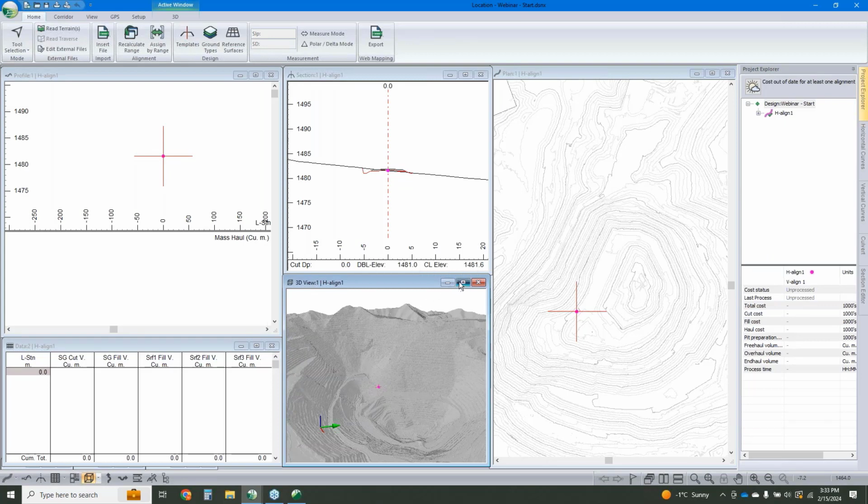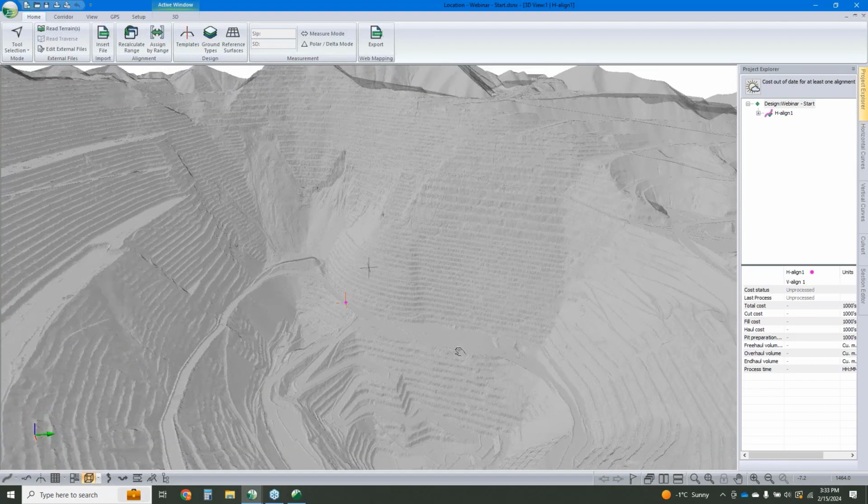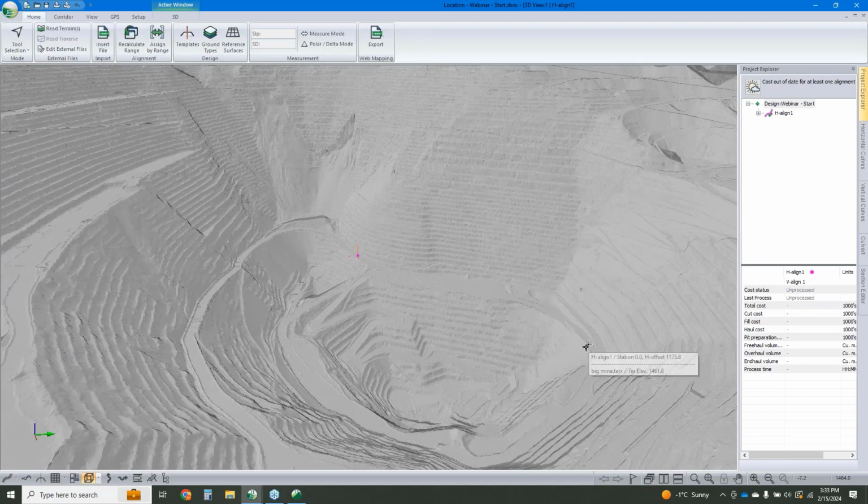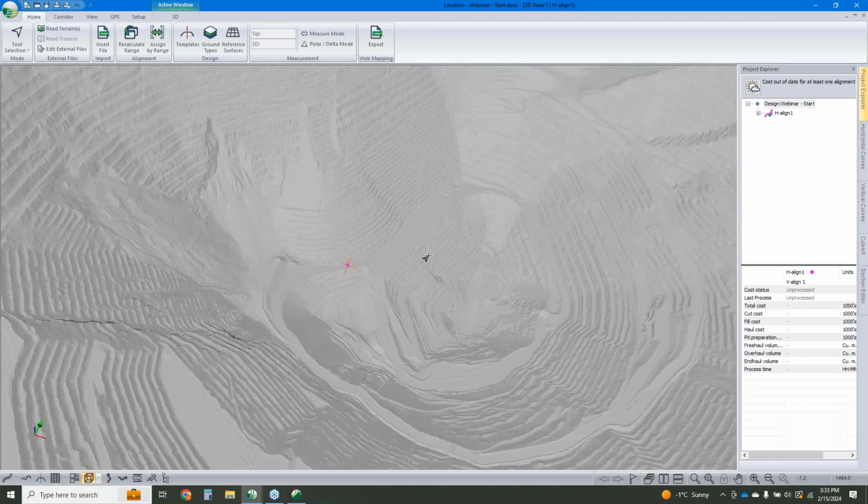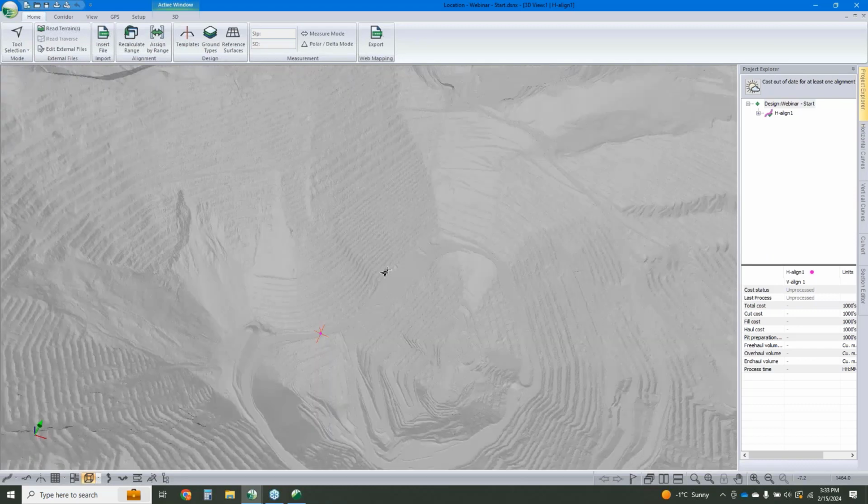But our goal, and I'll paint a little bit of a picture, tell a bit of a story: this rather large pit, we want to continue developing it. The plan is to excavate where the existing pit ramp to the bottom is. And we're also going to want to set ourselves up to continue developing this pit out, so push the pit walls back as far as we can without actually taking down the rest of the wall itself. Now, in doing that, we're going to want some special cross-section considerations here that deviate from that typical access road or even a surface haul road in a lot of cases.